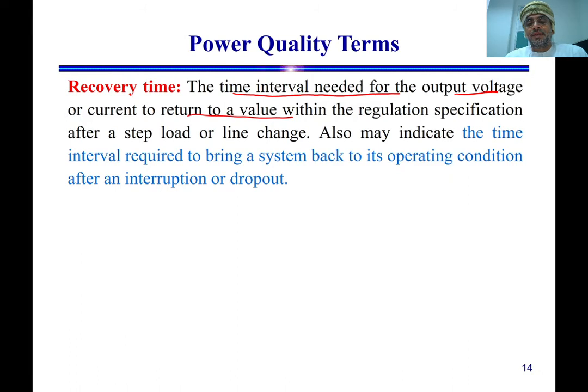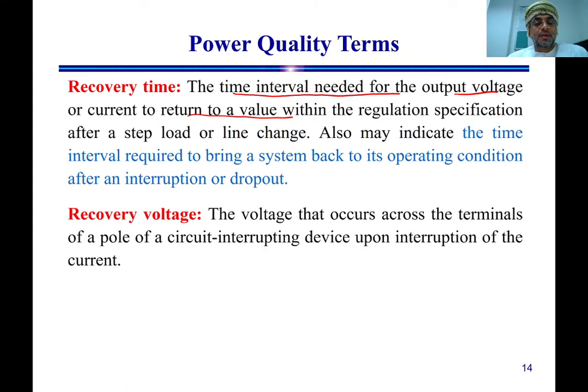Also, it may indicate the time interval required to bring a system back to its operating condition after an interruption, or dropout. This is for the recovery time, but for the recovery voltage, they define it as the voltage that occurs across the terminal of a pole of a circuit interrupting device upon interruption of the current.